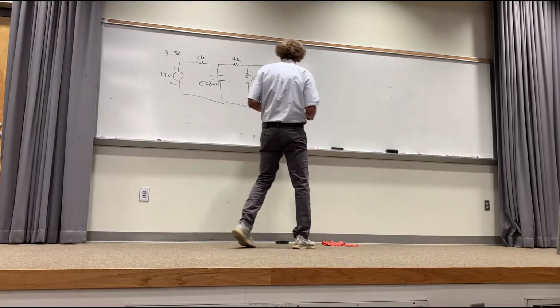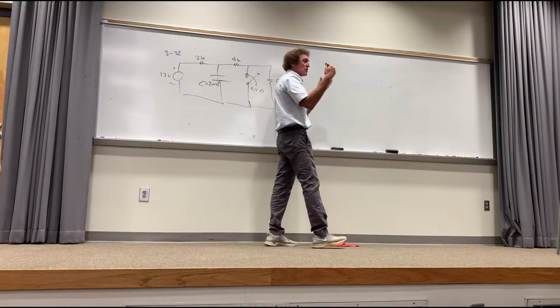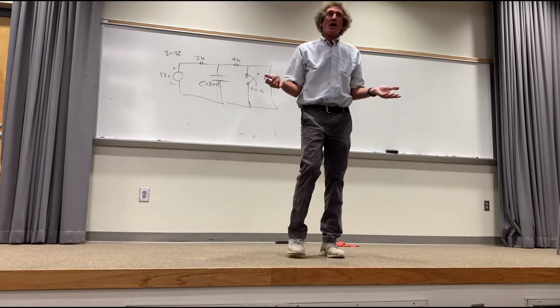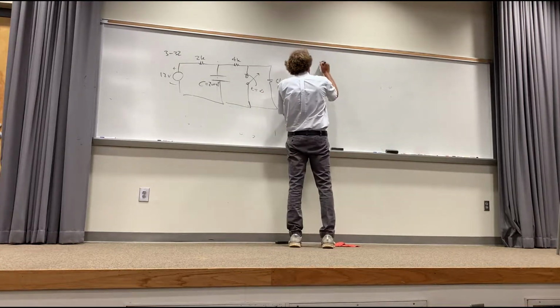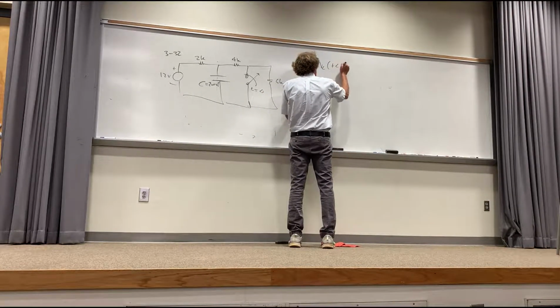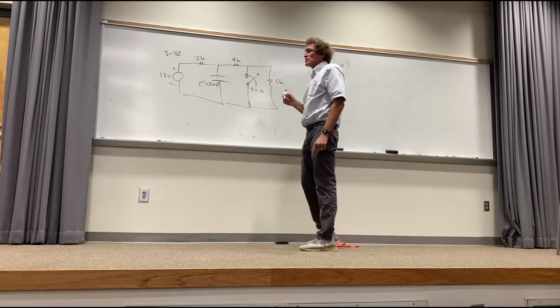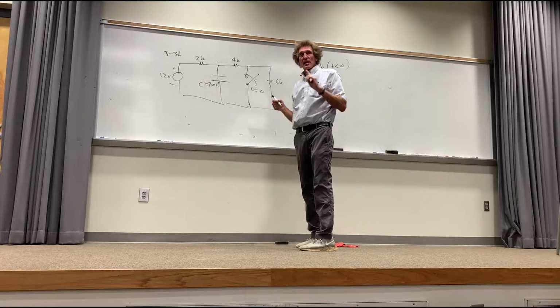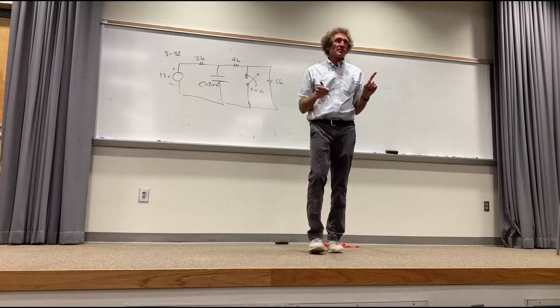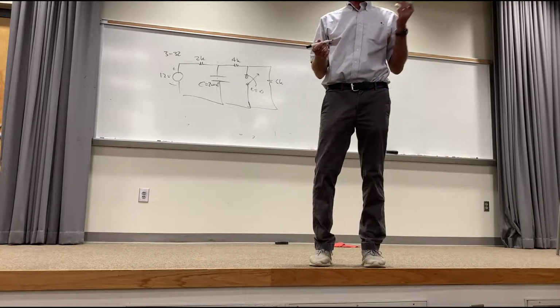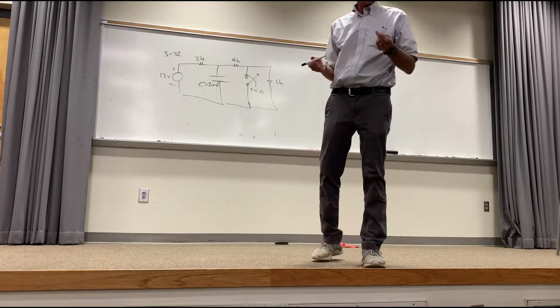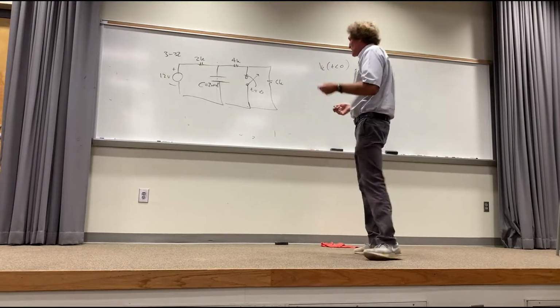Next thing I'm going to do is this. The order you do the steps is not important. I always start with the voltage across the capacitor for t less than 0. So I'll draw the circuit one time. What does a capacitor look like for t less than 0? It's an open circuit, right? Nothing's changing. Do you all agree with me? So a capacitor looks like an open circuit if nothing's changing.